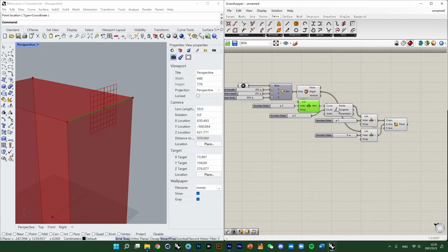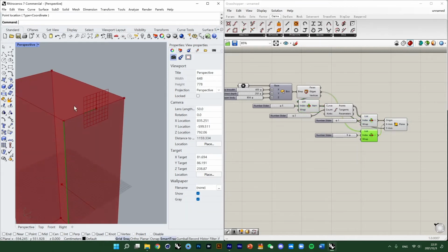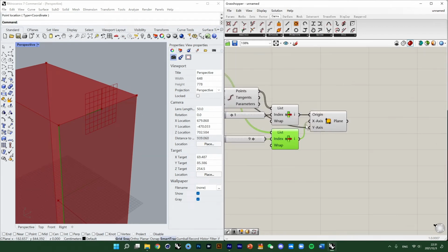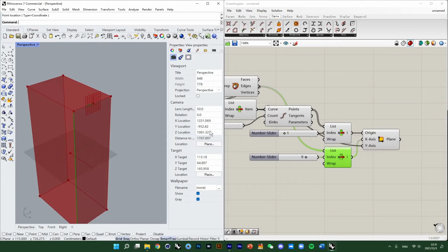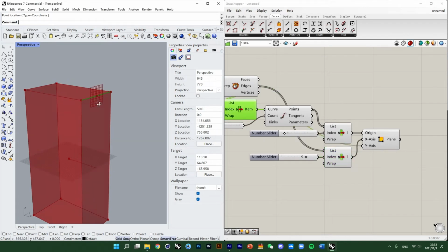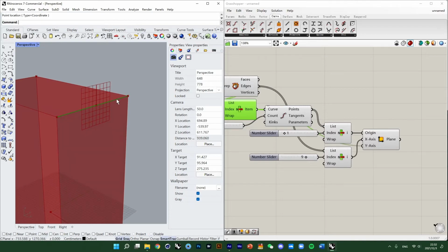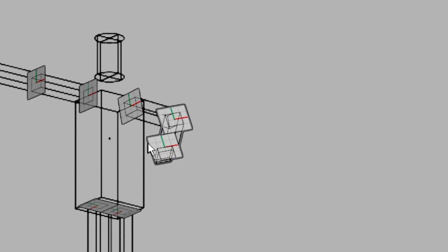We don't want universal axis to define our plane because universal axis won't follow our rotation. It will always face one direction, and that's what we don't want. We need our plane to follow the rotation of the parent object and always keep the rotation with our parent object, as I showed in our construct plane before.